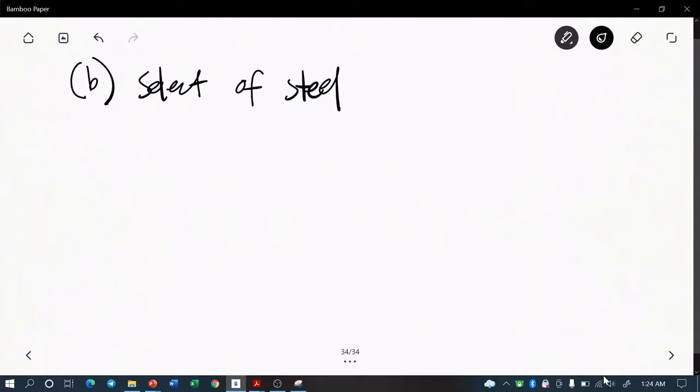Prior to selecting the material, we should solve the S sub y. This S sub y is our prerequisite in order for us to look up a material which has the closest value of this S sub y in the tables of engineering materials. It could be table 88 or table 87. But first let's solve for the design stress.